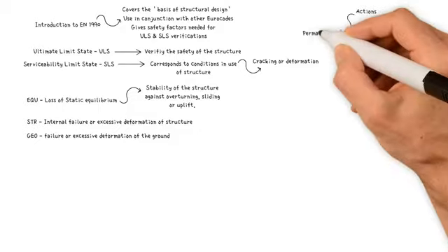When considering a limit state of rupture or excessive deformation of a section, member or connection, STR for the superstructure and the STR component of STR, GEO for the structural design of the foundations, the verification will need to ensure that the design value of the effect of actions, such as moment, is equal or less than the design value of the corresponding resistance. Actions may be permanent, for example self-weight of structure, fittings and fixed equipment, or variable, for example, weight of occupants, wind and snow loads.